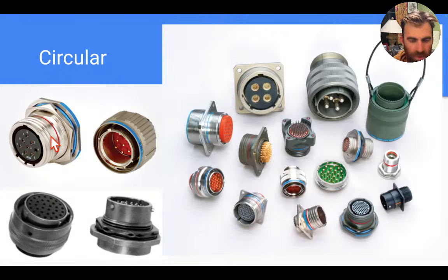So you would connect the connectors together and twist it, and you would hear a ratcheting noise as it tightens down. And then once the connector shell is tightened down, it's going to cover up this red line to indicate that the connector is connected fully. So that's a visual indication of proper connection.